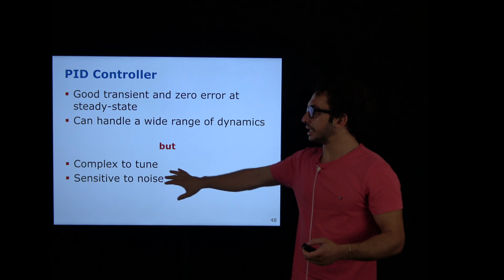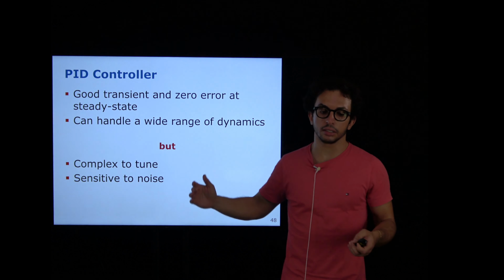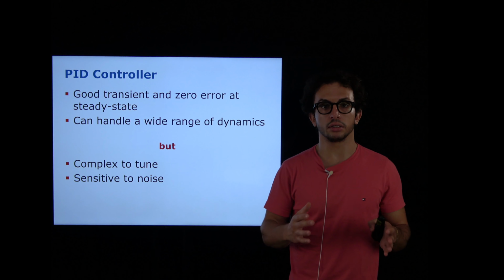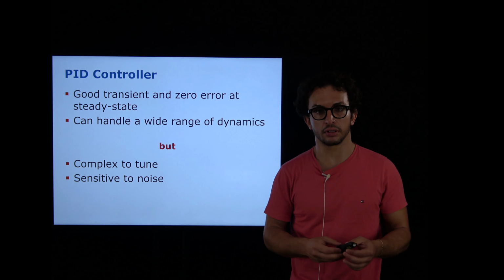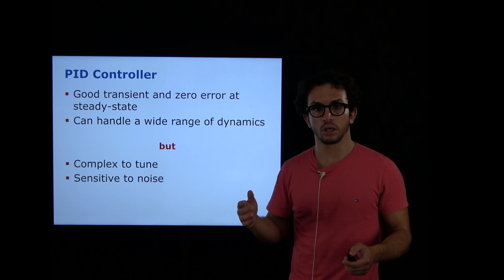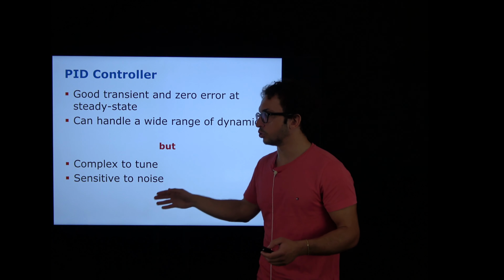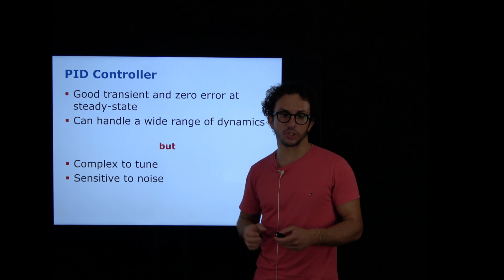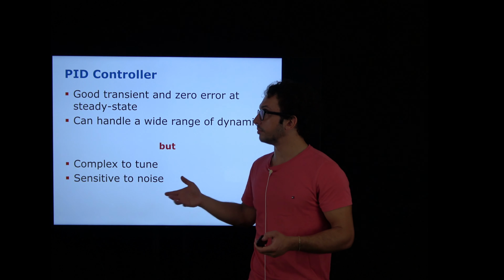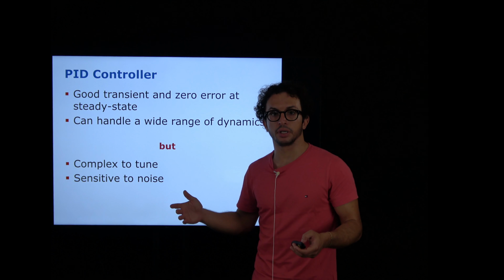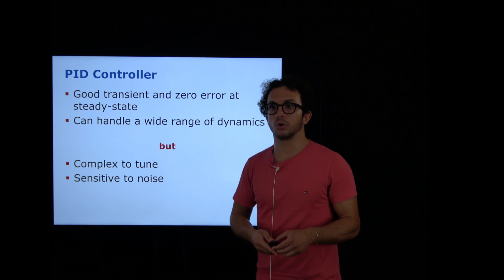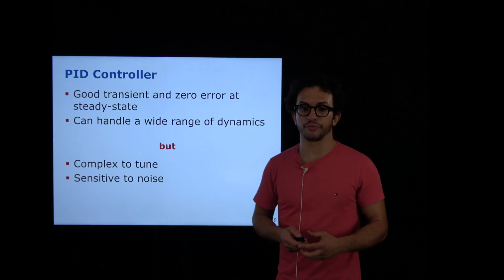And also the PID, I haven't written it here, but I think that now you have an idea of the fact that the PID might have the wind-up effect. And so it's something that you have to consider and deal with. You have to decide how to take care of the integrator part when the saturation might happen, if it can happen in your system. So this is something that has to be taken care of.